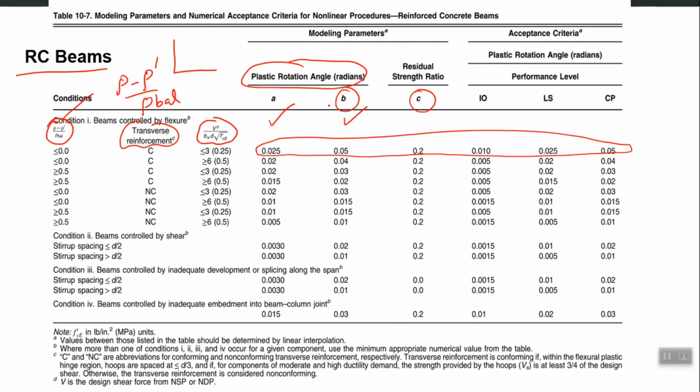If I follow this first row, I should be able to develop this kind of behavior for my beam, in which on the y axis you have the moment, and at this particular location this is my. This my you should calculate yourself. It will be a function of fc prime, fy, amount of steel and everything. You can use some simplified method to calculate my. It can be Whitney's approach also. This is the moment capacity of your beam.